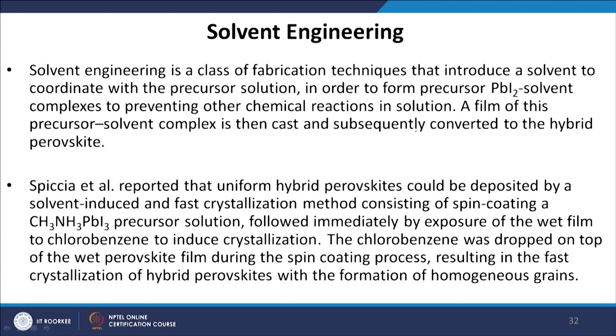Solvent engineering is a class of fabrication technique that introduces a solvent to coordinate with the precursor solution in order to form a precursor lead iodide solvent complex, preventing other chemical reactions in solution. A film of this precursor solvent complex is then cast and subsequently converted to the hybrid perovskite.